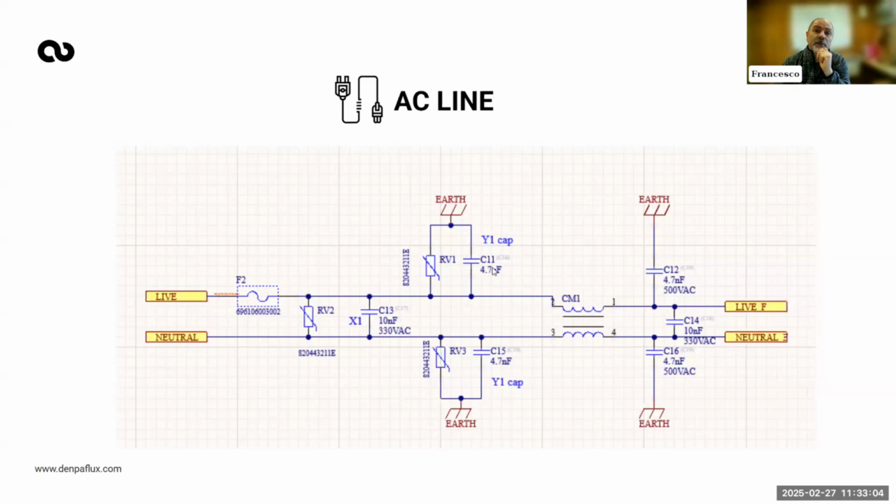So, for example, in this particular design, I'm still using a fuse as before, an anti-surge fuse, because I know that between live and neutral we are going to do a lot of surge tests, and surge tests are very, very demanding. This time I have used the symbol that I usually use for varistor, because the energy you use between live and neutral is usually much higher. And you need a varistor that survives this.